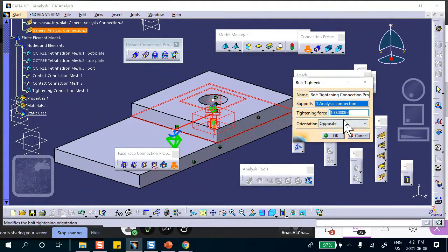In other words, when you clamp two things together for precision purposes, you don't do it with a hand. You use a torque wrench in order to find out what is the force, what is the moment, and that translates into force. And since you're fourth-year students, you have done bolts and things like that probably in your design for failure prevention course. So I put down 50 because that's what the problem said. And I have no idea. Is it too much? Is it too little? If it's too much, it may break the bolt by plastically deforming it. If it's too little, that's not enough clamping force, etc.